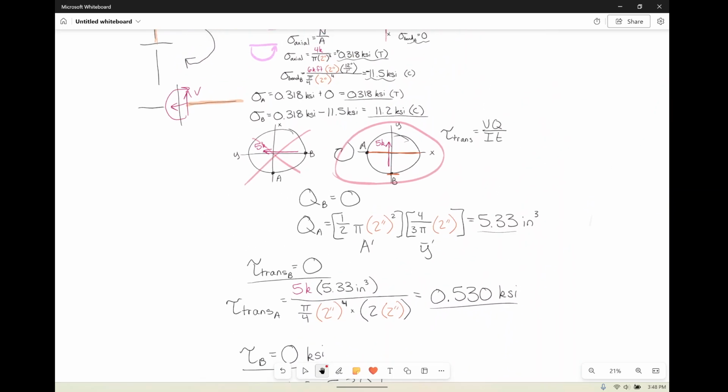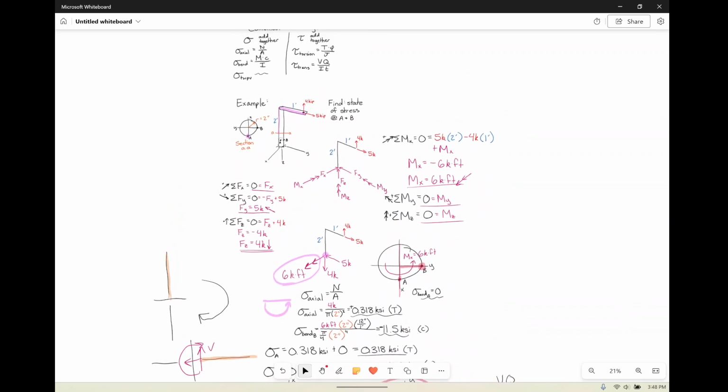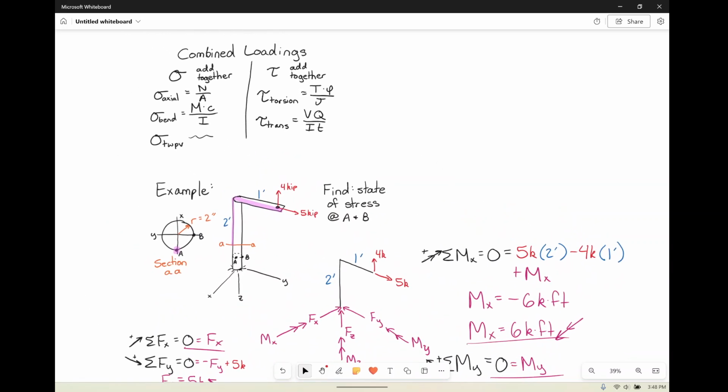So you see, it's actually not too complex. It's simply the same problems you've been doing over and over again, except now we're bringing it all together as one. So again, we first need to do statics, figure out all of our forces, and then see, as individual separate problems, which direction those forces create stresses, and whether they add together because they're both positive, cool, or don't add together because one's positive and one's negative.